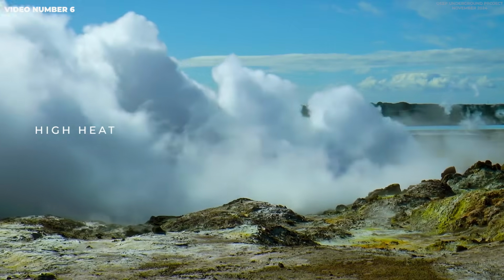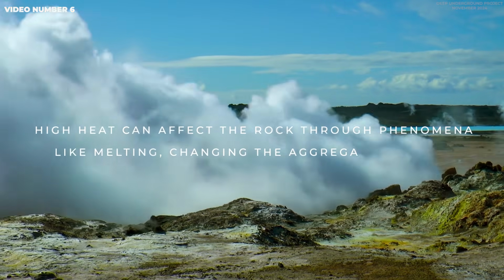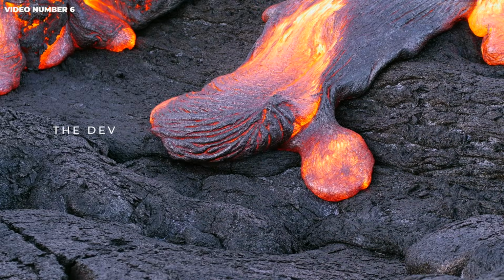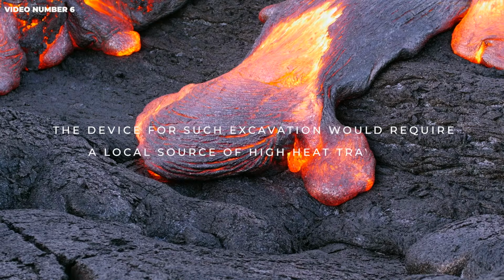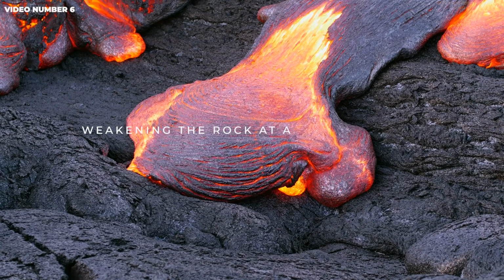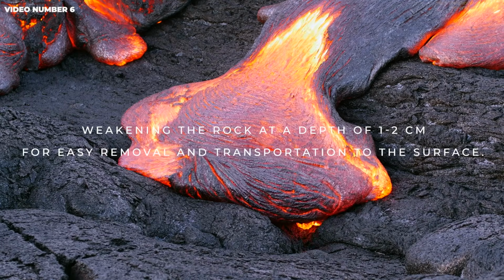Heat. High heat can affect the rock through phenomena like melting, changing the aggregate state of rock ingredients, and recrystallization. The device for such excavation would require a local source of high heat traveling close to the borehole boundaries, weakening the rock at a depth of 1 to 2 centimeters for easy removal and transportation to the surface.